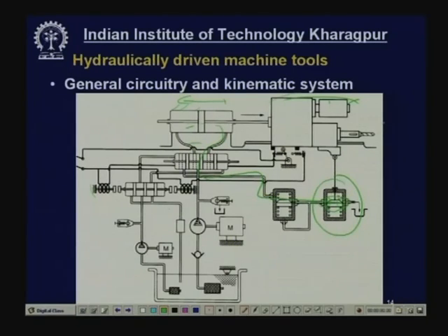Now, the movement of the spool is again controlled by this lever. There is a roller actuated by a cam. So, when this is moving forward first, then this is moving downward, allowing more opening. So, this will go faster. After that, this region will force it up and the opening will be closed, restricted. So, flow will be slower and the feed will become slow. So, quick traverse and then slow feed, slow back and quick return, all these things are controlled.